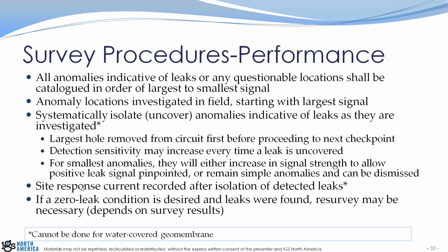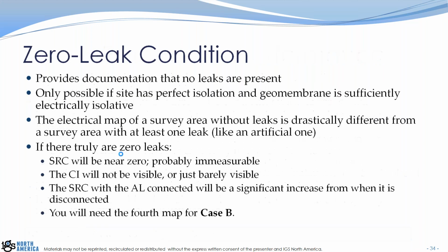So you want to make sure to record your site response current during this whole event, before, during, and after isolation of leaks. And if the zero leak condition is desired and the leaks were found during the survey, a resurvey may be necessary depending on the survey results. There are some sites, especially if they don't have cover material that's extremely conductive, where you can find every hole, big and small, because the current can't travel very easily through that material, so it gets distributed better. But it's just one of those things that requires expertise.